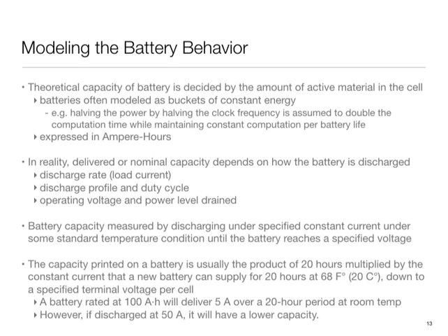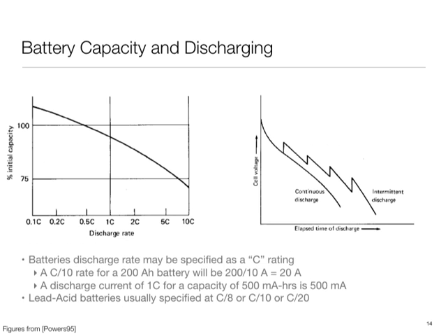The way these curves look is they are kind of flat and then they fall. You would see these kinds of curves in a real data sheet, where for the rated current there will be some capacity and then the curve goes like that. So this is one non-ideality that we need to somehow model: the dependence upon the current. But things are a little bit more complicated. This is the part I was mentioning earlier: you take your flashlight, it dies, and then you wait and it comes back up again.